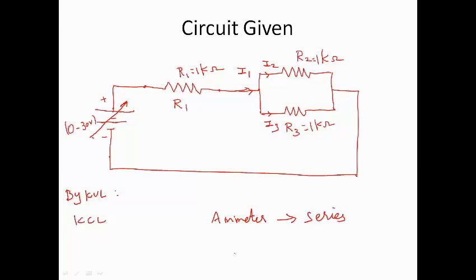And to measure voltages we have a voltmeter, and this voltmeter should be connected in parallel across the points. Okay, so for this circuit now you need to draw a practical circuit for the given circuit. How to draw the practical circuit means you have to incorporate those meters at appropriate places.